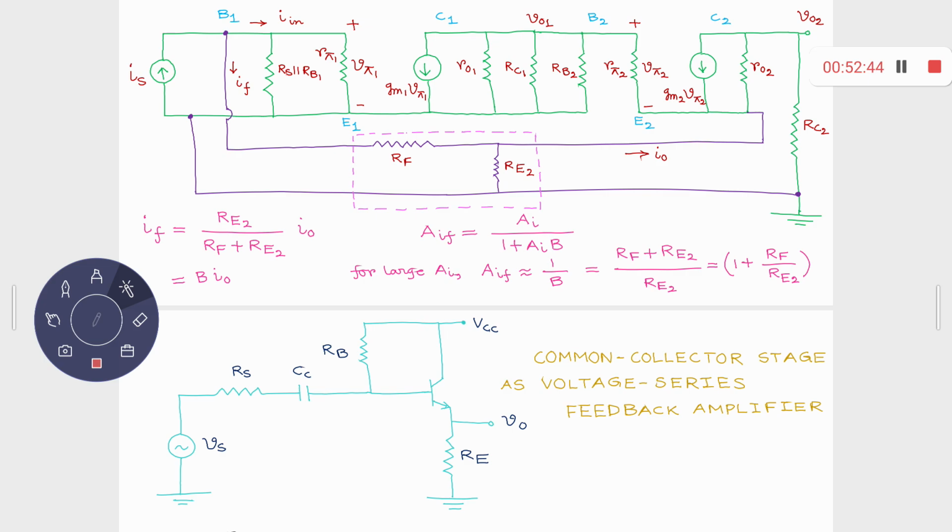Now, if I ask you to check whether this particular circuit is a feedback amplifier, you can always draw the small signal model for this. You have drawn it previously many times. Now, this time you have to draw the small signal model in such a way that it looks like a feedback amplifier. It must be having that resemblance: this feed network, this feedback network, and that connection. That is important. You don't get this anywhere in any book. You don't get it.